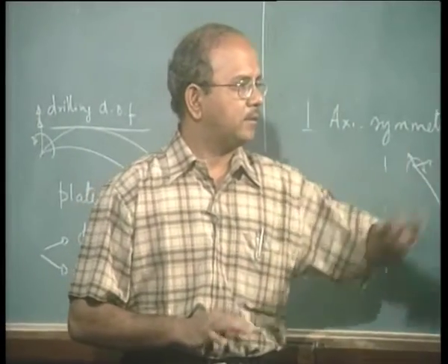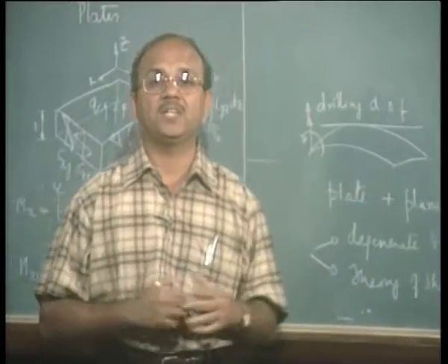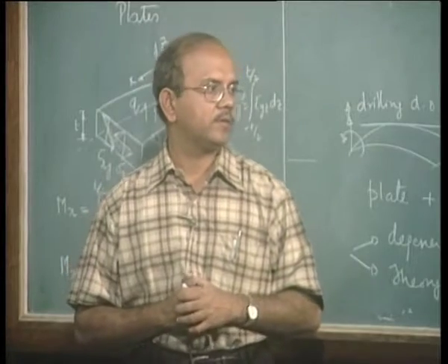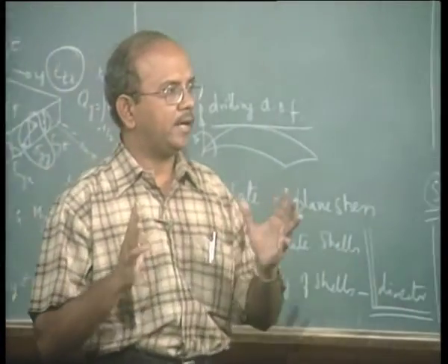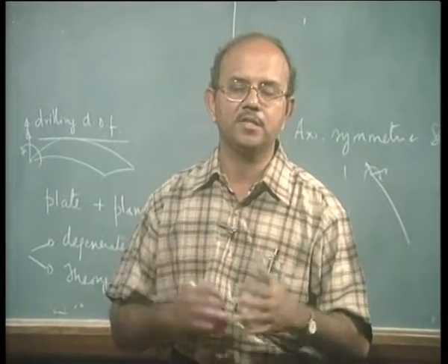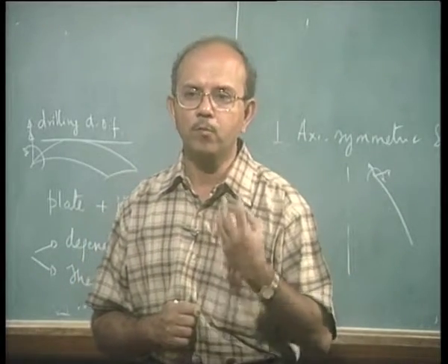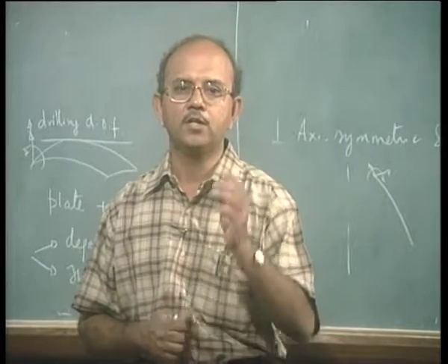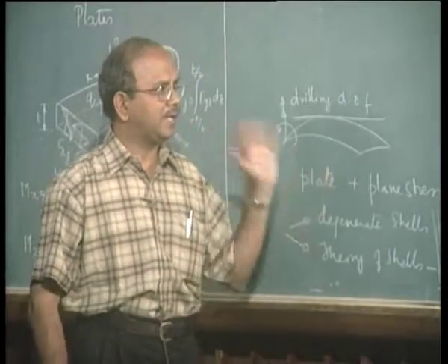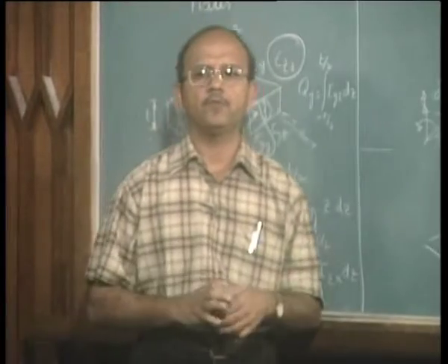So, that part we covered, and we also looked at how to model heat transfer problems, both transient as well as steady state. There again we had an approach which we call a semi discretization approach, and if you remember, we used some of the well known principles from finite difference in order to work out problems in finite elements. And lastly, we have seen an overall picture of the shell element formulations.